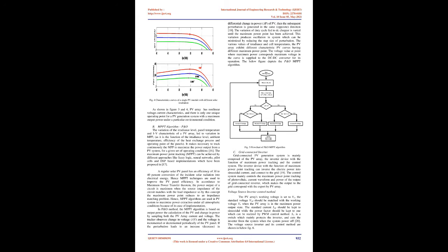In accordance with the maximum power transfer theorem, the power output of a circuit is maximum when the source impedance of the circuit matches the load impedance. So by this concept, the maximum power point reduces to an impedance matching problem. Hence, MPPT algorithms are used in PV systems to maximize power extraction under all atmospheric conditions because of their ease